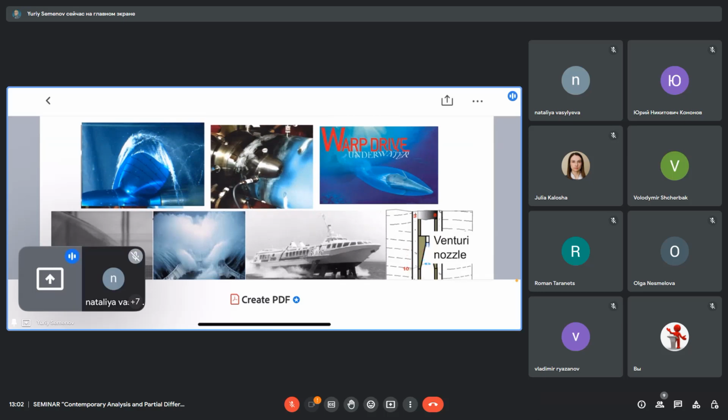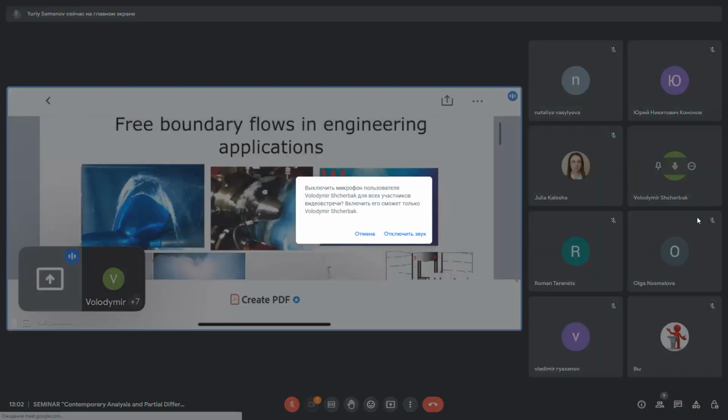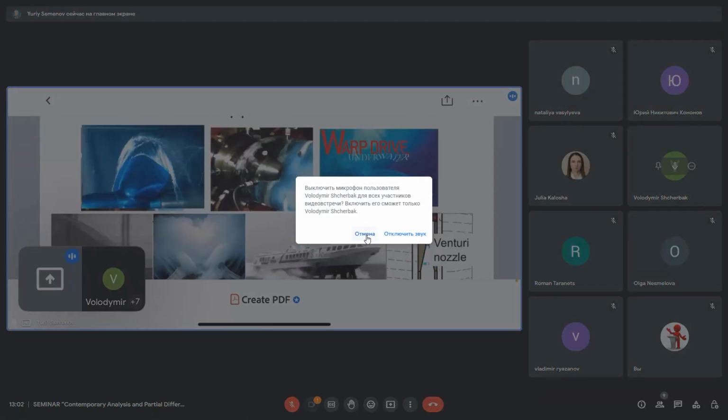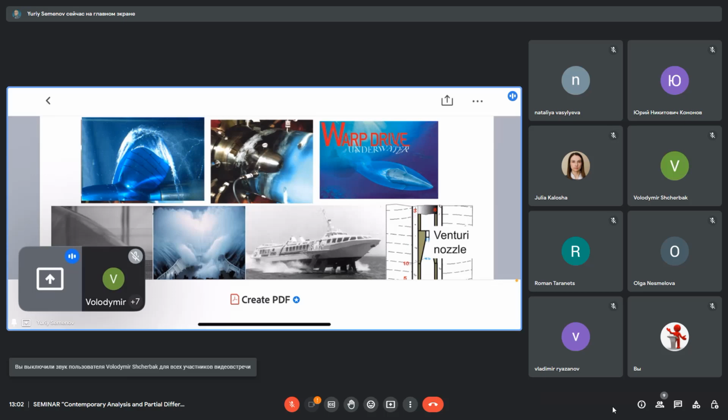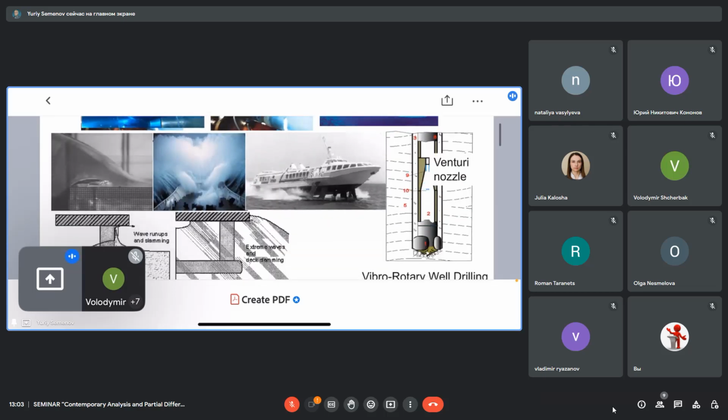One sort of fluid mechanics problem arising in industrial applications are those dealing with free boundaries. Free boundary problems are nonlinear because the flow region is unknown and has to be determined as part of the solution. You can see cavitation in a marine propeller, cavitation in an inducer of a centrifugal pump, supercavitation, torpedo, rocket. As you know, this is the topic of my department and the Institute of Hydromechanics, where this technology was invented by the famous Professor Logvinovich, Vladimir Georgievich.